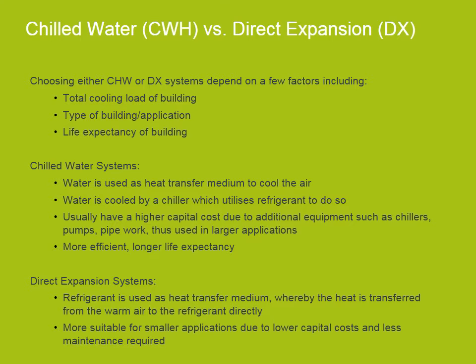Whereas for direct expansion systems, the refrigerant itself is pumped to air handling units from the compressor and the heat transfer occurs from the air to the refrigerant directly. These are more suitable for smaller applications due to their lower capital costs and less maintenance required.